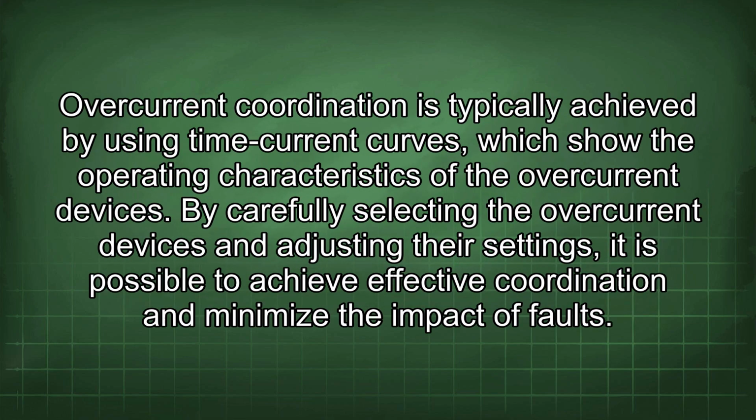Overcurrent coordination is typically achieved by using time current curves, which show the operating characteristics of the overcurrent devices.